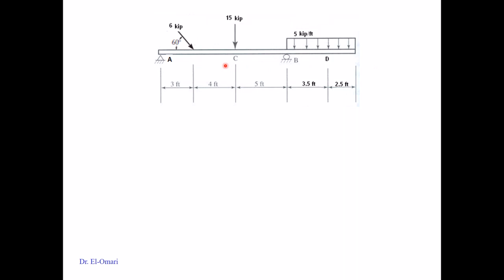You notice the right hand side has the support reaction at B_y. It is a roller support, which means that I first have to find it from the whole system before taking the cut. So the best way to find that is moment about point A, and then you write the moment equation. So you have B_y times the moment arm.